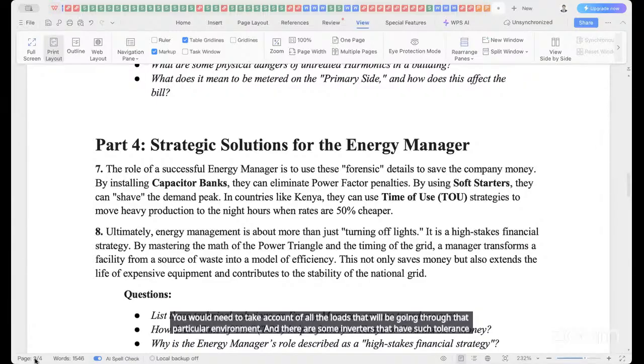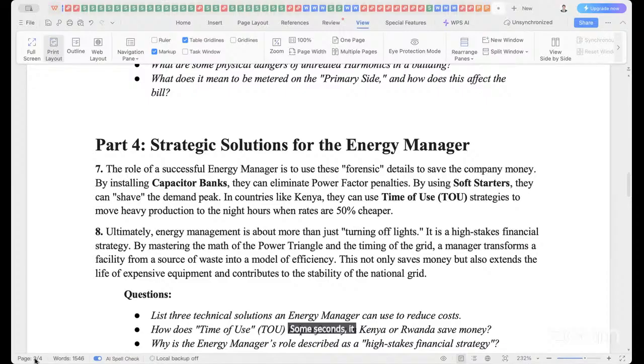For instance, if the inverter is 10 kVA, sometimes it has a temporary surge output of 2 times its rated capacity. So for some seconds, it can output up to 20 to 30 kVA. So using the right inverter at the beginning of setting up the system can go a long way in ensuring that there's no system collapse.